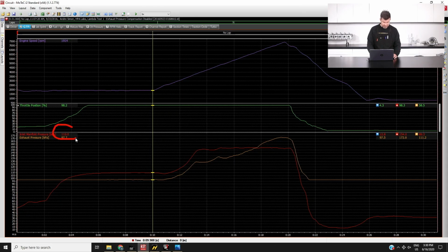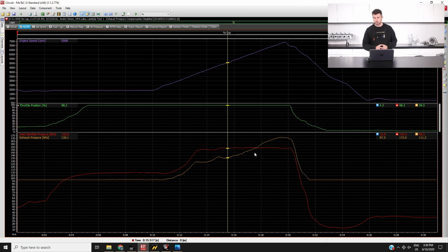It's probably a little bit hard to tell, but we've got our inlet manifold pressure at 110 kPa, so just slightly above atmospheric on that particular day. Here at altitude we're around about 97-98 kPa normally, and you can see that that's exactly what we've got from our exhaust back pressure. We end up with this run, our peak boost is running through about 150 kPa. If you're wondering why the numbers are so small, bear in mind that this is on a naturally aspirated Subaru FA20. I think also at this point we were still running pump gas, so we're trying to keep the boost relatively low in order to keep the engine sort of knock free.